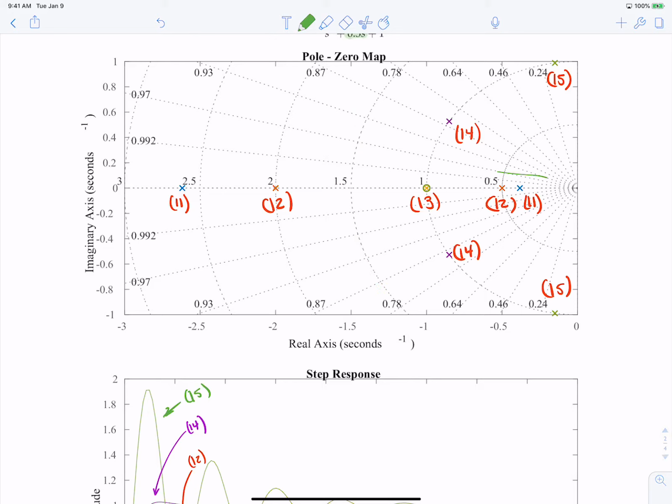Okay, so these radial plots going out like this, these are actually constant lines of damping ratio. Let's translate that back. All the roots that were on the real axis have a damping ratio of exactly 1. It's perfect damping. Awesome. And you can see all those roots gave us a nice, clean response, a natural decay response. But let's look at equation 14.